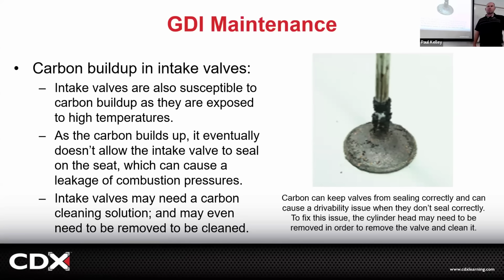Walnut blasting is another common thing. You actually close the valve and you literally blast air-pressured walnuts onto this and it'll break all that up, and then you vacuum up the dirty busted walnuts. It sounds crazy, right? But it's true. We're doing more maintenance on these. Everything's great about the power and the better fuel economy and emissions, but then the customer's like, I got 60,000 miles and a misfire, and you're telling me I need to clean my valves and clean my injectors? Like, this system sucks. But it's like, well, it gave you the better fuel economy and emissions, but it needs more maintenance. I'm sorry. It just is what it is.